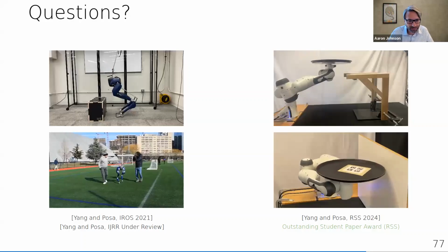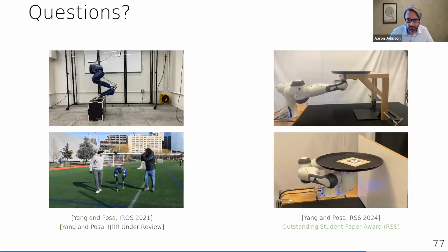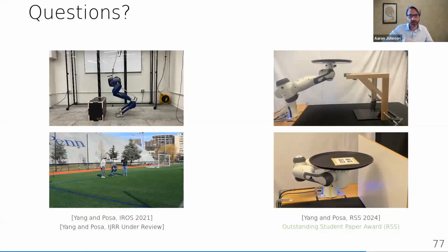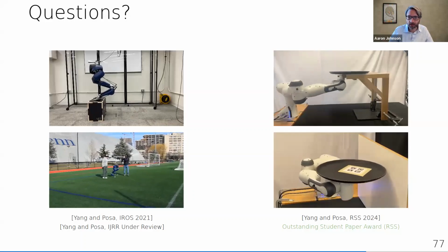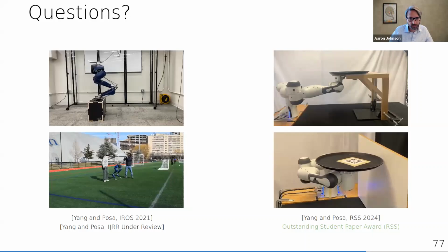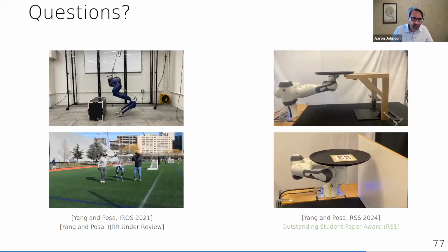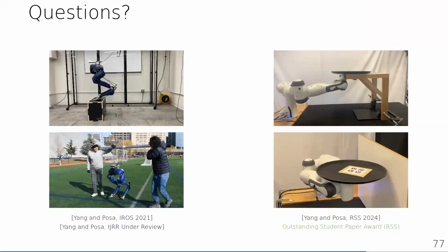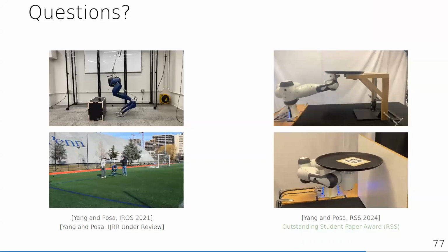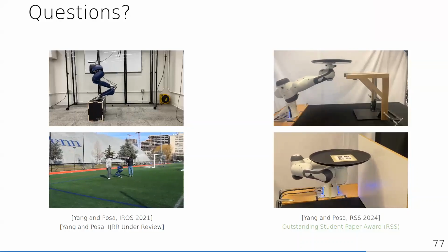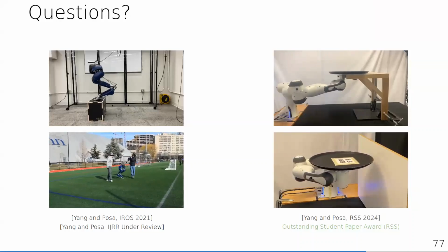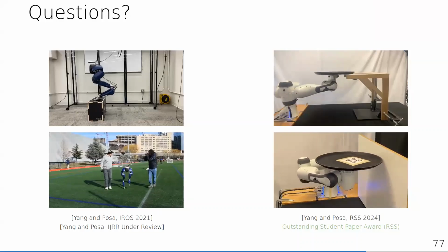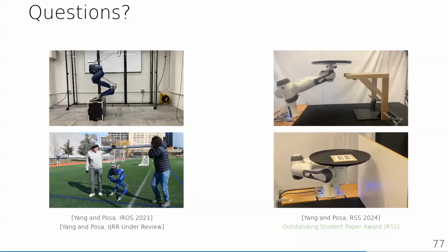I had a couple of questions. Thinking back to the first half, the impact and variance stuff. When you say that the impact takes this amount of time, is it really that the impact takes that much time, or that once you have an impact, it takes time to propagate up to these other joints in the robot? I think it's both. The compliance in the joints can definitely add to when different joints feel the impact, but also even just a solid rigid object that touches the ground, that impact doesn't resolve instantaneously, and even a very rigid object could still take on the order of 10 milliseconds to resolve.